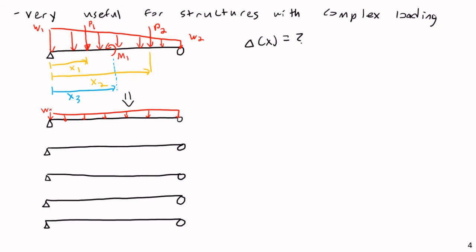With magnitude W2, then I could have the linear, decreasing portion here that goes from, well, it would not be W1, it would be basically W1 minus W2, because I want just the triangular portion of the load there.